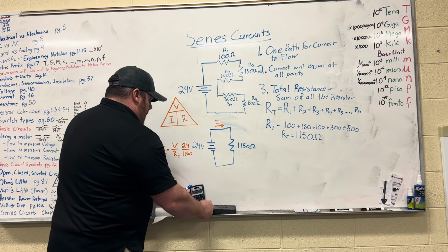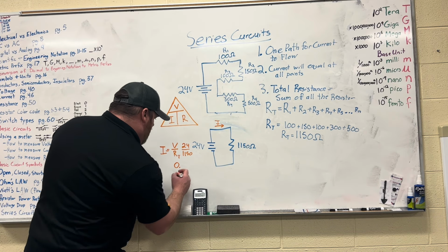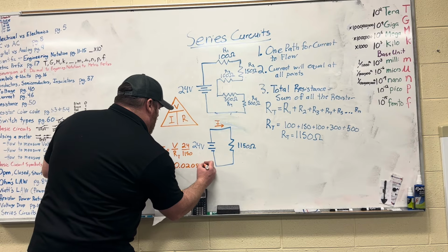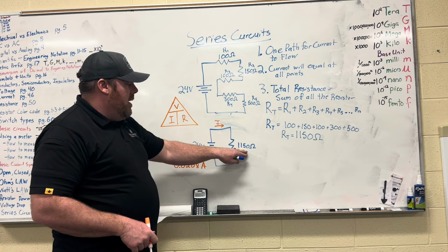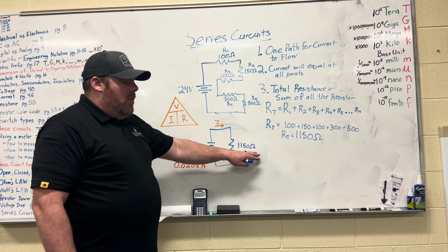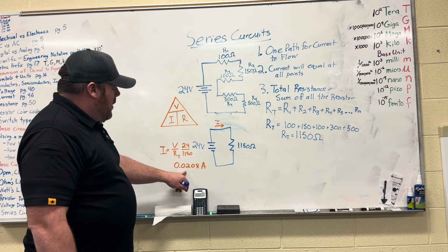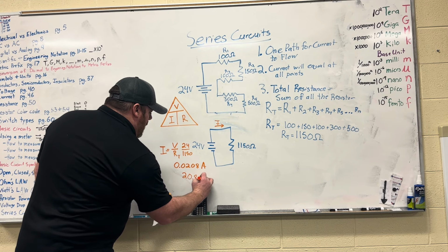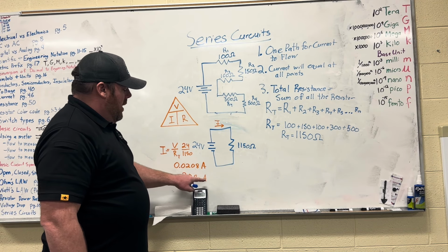The number that we get in the calculator is going to look like this, and this would be in amps. Very important to remember that the units have to be in their base units. This can't be kilovolts or milli ohms or mega ohms. It needs to be in volts and ohms in order to get amps. But once we get this value, this would be the same as saying 20.8 milliamps. Move the decimal 3 times back, that would be 20.8 milliamps.